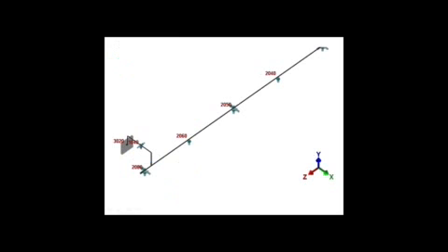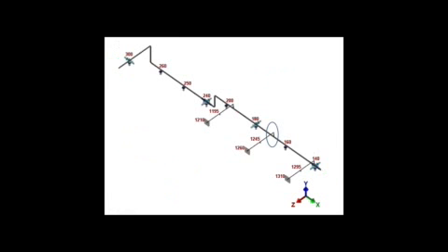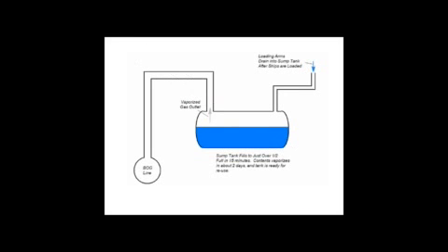So now in this system, we look at it again. Here I see local flexibilities. So in this case, we probably never worry about this. This is something that somebody analyzed. The guy that put this system in probably knew what he was doing. The guy that put this next system in just didn't provide enough of an offset. If he ran Caesar, he got all the extra flexibility from the surface to the center line. It showed okay, but not really okay.